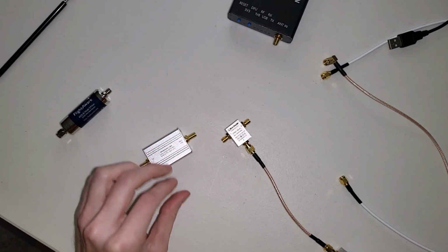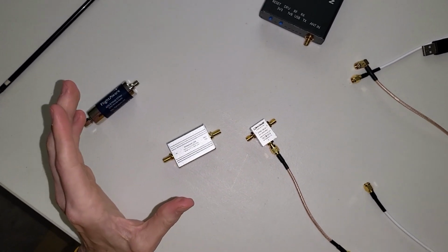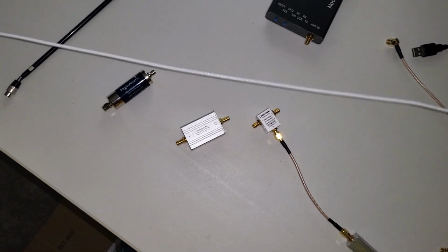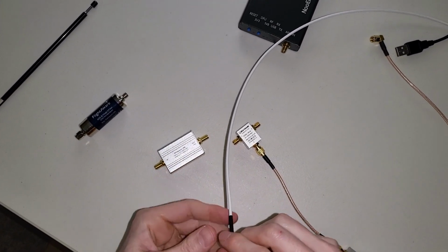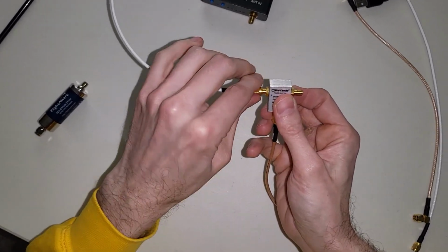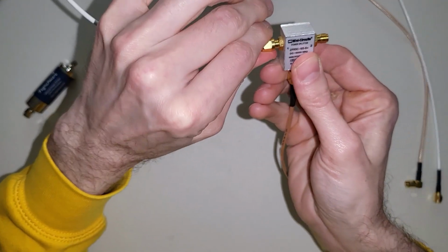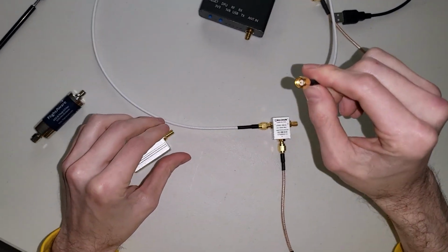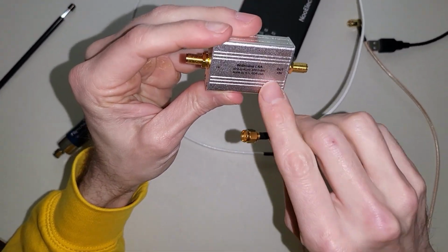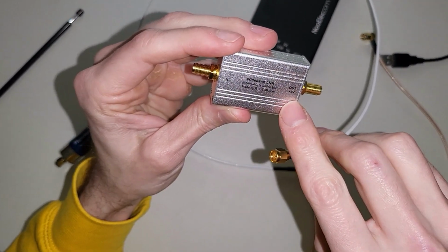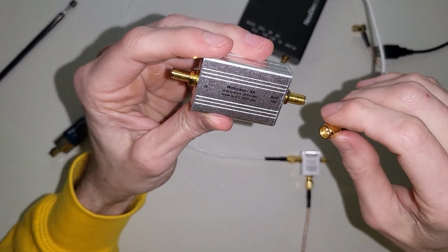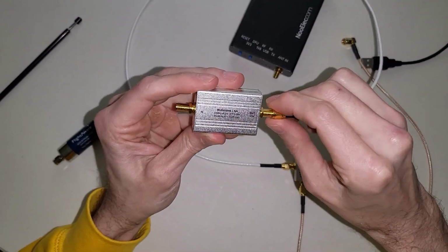All right, next we'll hook up the LNA and the filter and the antenna. So using a long SMA cable, this one's a little over a foot, go ahead and connect one end of this to the power combiner. Then hook the other end of this cable to the port on the LNA that's labeled out plus 5-volt. This is important. You want to ensure you're connecting to the out port because this is the port that will accept the DC voltage from the bias T in the dongle. So go ahead and hook that to out.